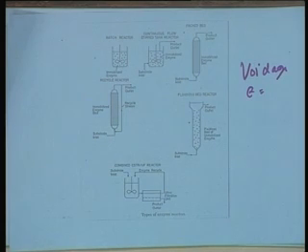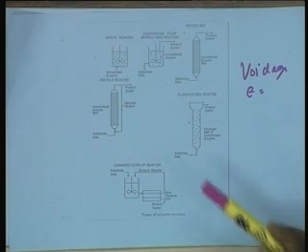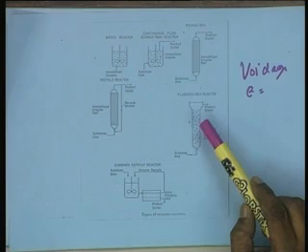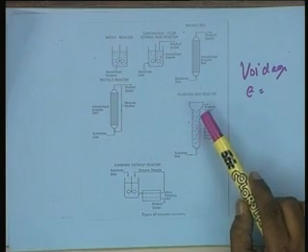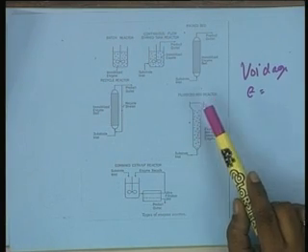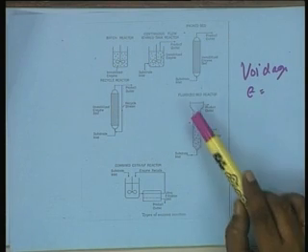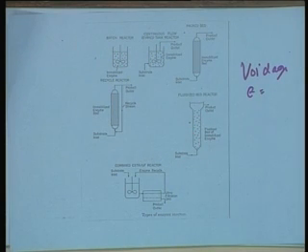But when you move ahead from the plug flow behavior and continue to increase your feed velocity to a level at which the packed bed is disturbed, it gets fluidized. The particles are fluidized in the reactor system, almost like as shown here in the reactor, but not to the extent that the catalyst particles are driven out of the reactor system. They are retained in the reactor system. We call it a fluidized bed immobilized enzyme reactor.